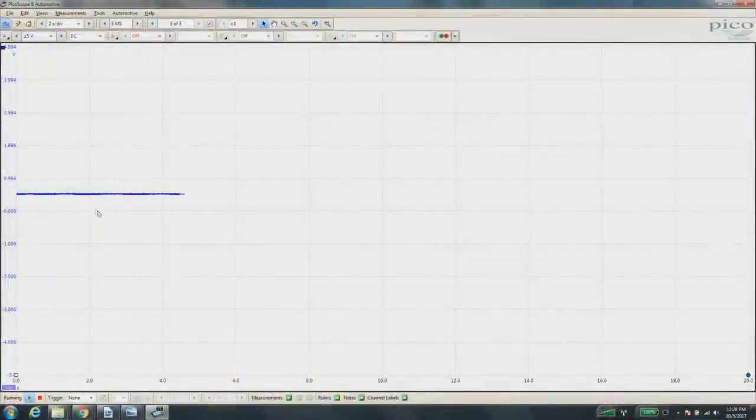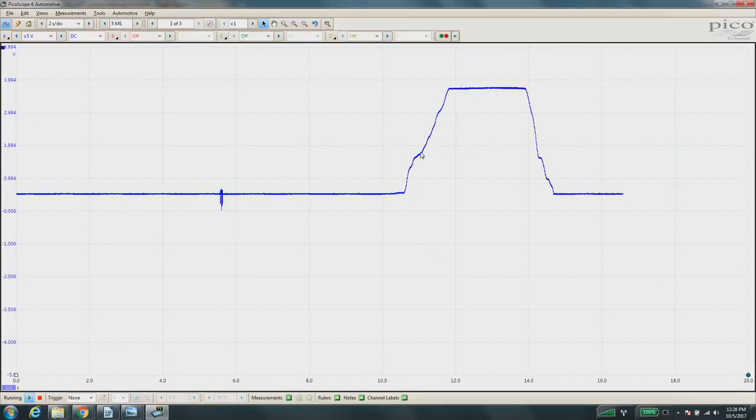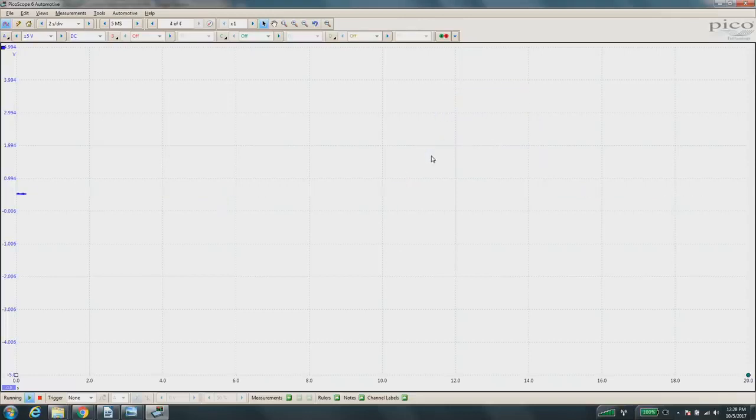go ahead and sweep the throttle position. Go ahead whenever you're ready. Yep. There we go. And back. Unfortunately, like I said, this one's not dropping out at all right now. Go ahead and do it a couple more times. What we're looking for is just spots in here where our... oh, here we go. Beautiful. All right, you can stop there.